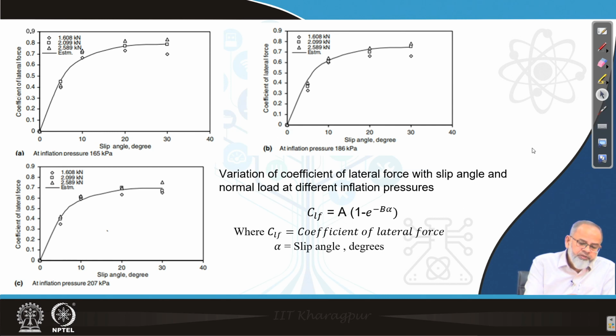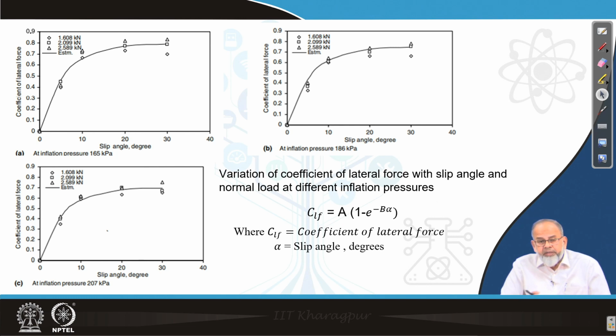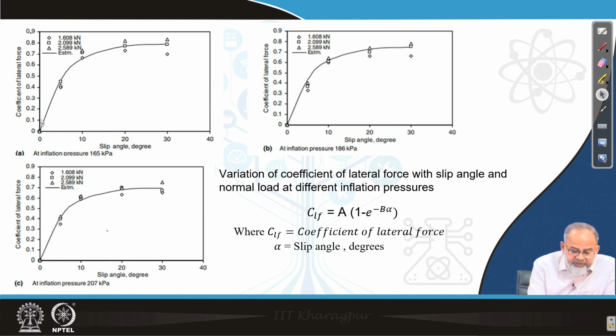When you plot the coefficient of lateral force for 3 different inflation pressures and different normal loads, what we observed is that it is basically an exponential relationship which is fitted for all these 3 conditions, whether it is inflation pressure 165 kilopascal, 186 kilopascal, or 207 kilopascal.